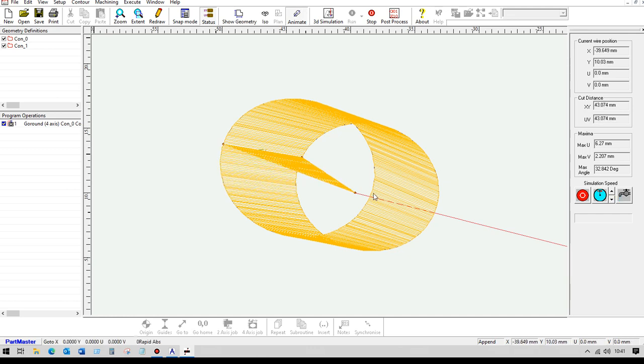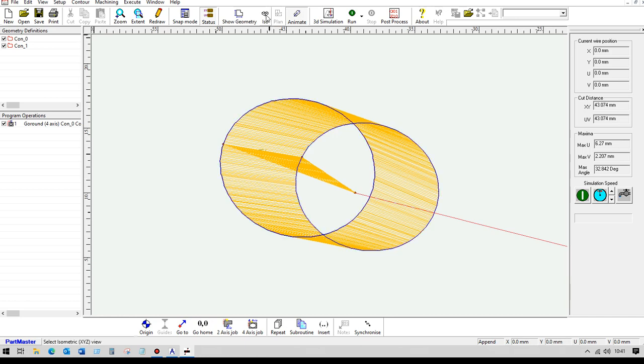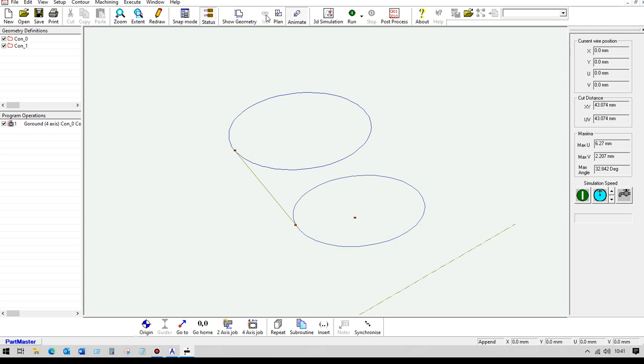Now in this case the pilot hole position I've set as 5mm, but you can adjust this to a known position. Note also that the start hole position, the pilot hole position, will need to be somewhere where it can be addressed vertically. Otherwise, how are you going to drill it? I suppose you could drill it on an angle. That's one way of doing it.